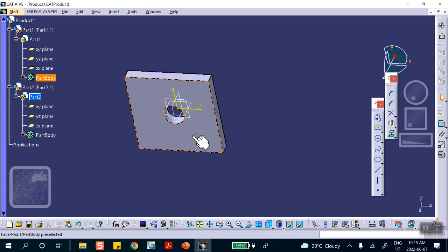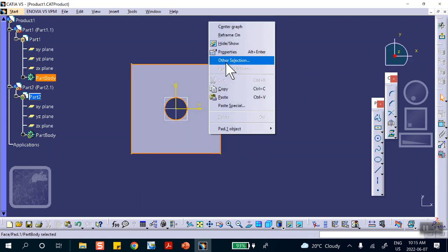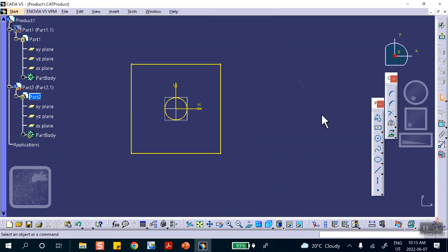So I'm not going to make that mistake here. I'm just going to project that face. When you project the face, it does the whole thing, goes down. It's going to give you a yellow rectangle and a yellow circle. Okay, so let me do that. There we are. The mistake that I made, I also projected that hole also. That gives me two circles on top of each other. Okay, so let's look at this. Now, I want to block this because I don't want to see it. That's because I'm lazy. I'm just going to delete this guy and do the rest of the rectangle.